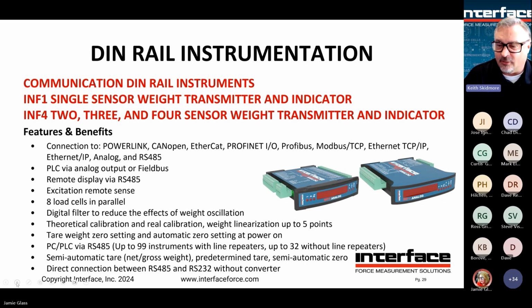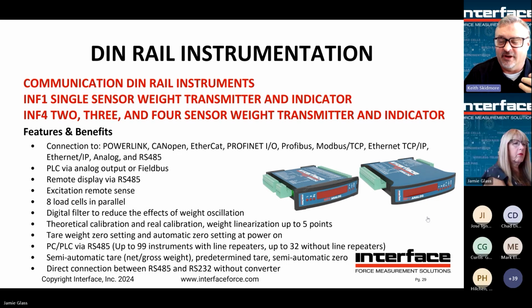The 4-channel ones are interesting. They are typically intended for scales and things for weighing applications where the sum of the channels is required. So it'll do some diagnostics and things. It'll tell you if one sensor is bad, which is useful in that way, but it doesn't necessarily let you easily look at each individual channel, because it wants to sum them up, and what's available over the field bus is the sum of the total, all the channels.